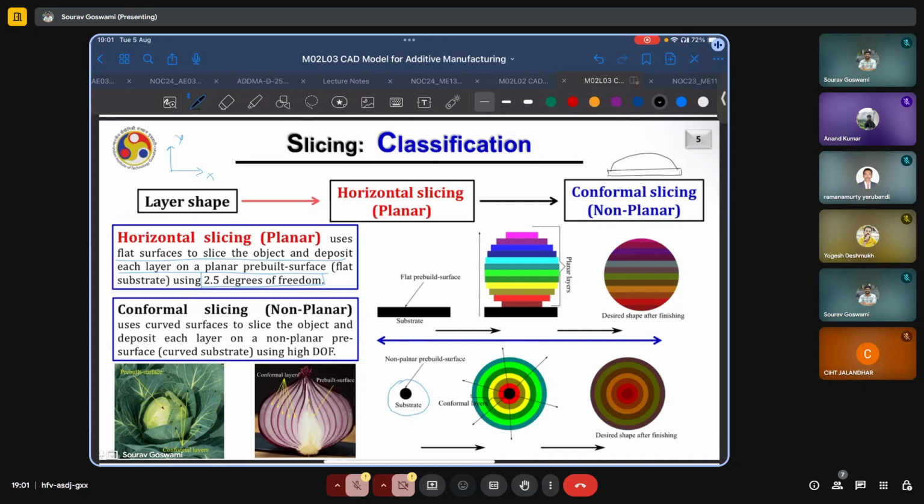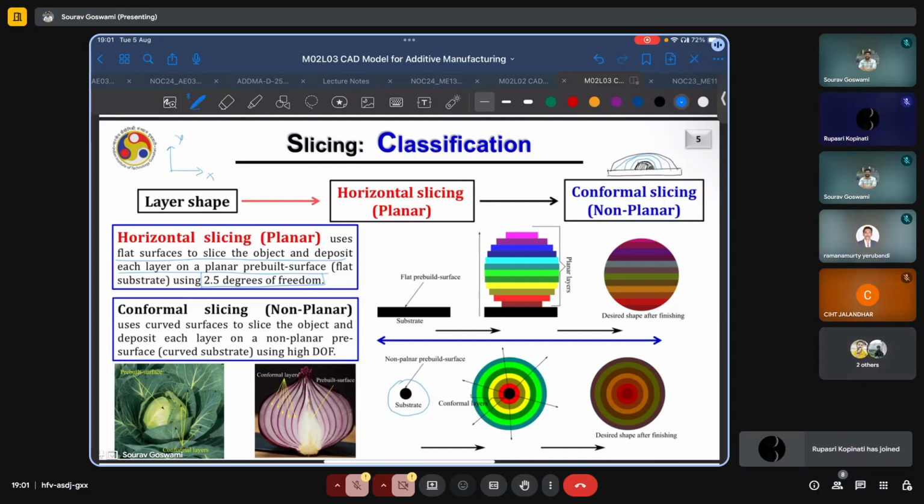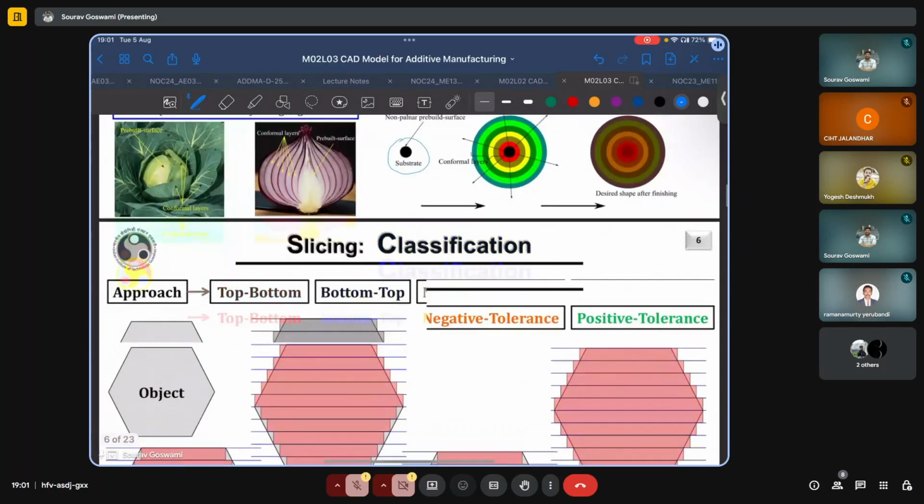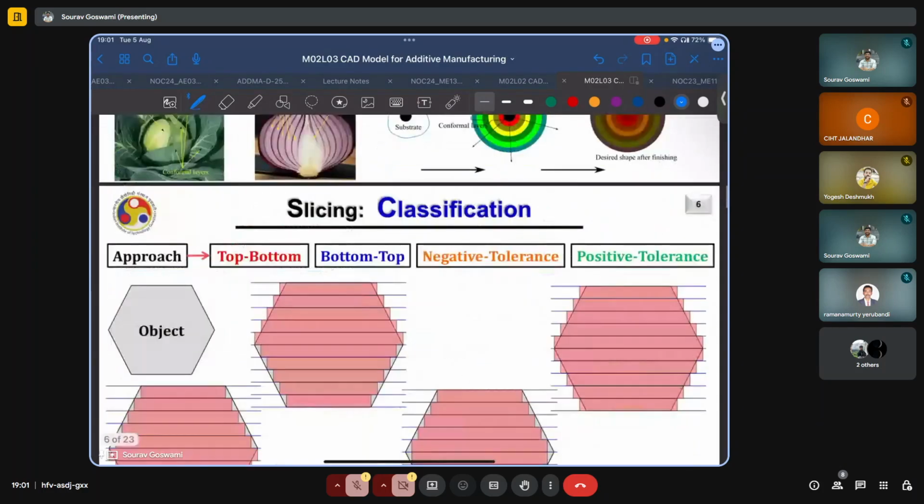And there we can start by having this hemispherical core, whether itself hollow or solid, and then we can have the layers deposited on top of it. And at the end of deposition, we can remove the core, or the core can be embedded, and we can end up with a hemispherical part, which will be very difficult to print otherwise.